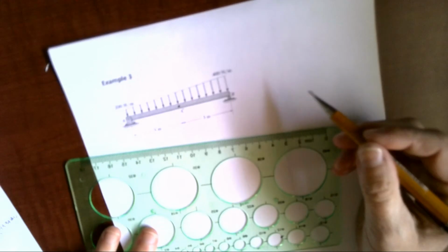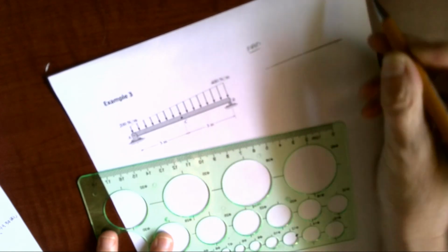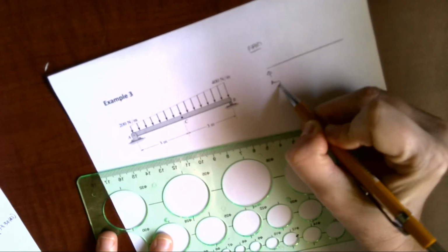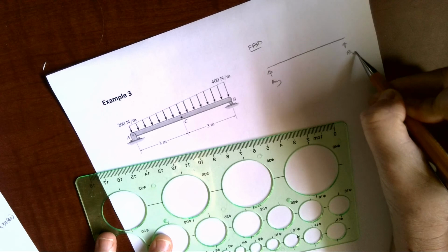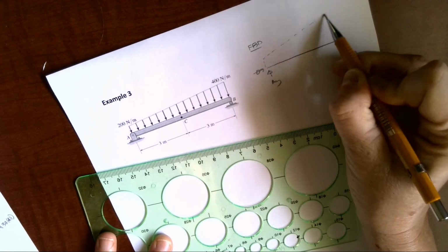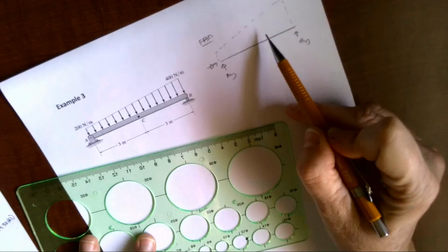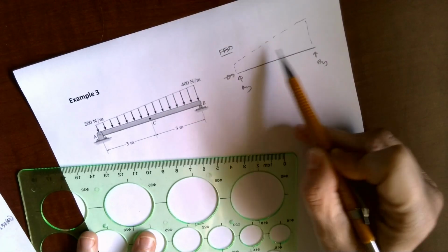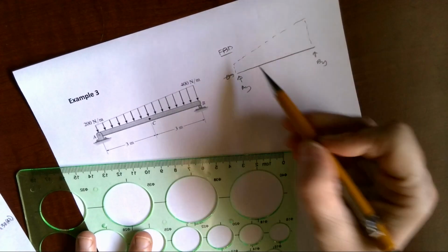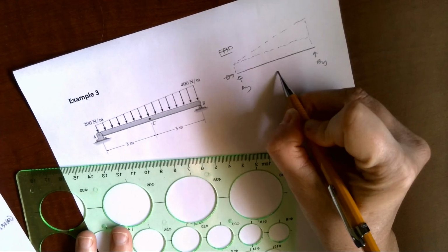So I'm going to draw a free body diagram overall, and I'm going to have an AY and a BY, and I know AX is 0 by observation. And then I have a load that looks something like this. Well, I don't really know what the equation is for the centroid of whatever this shape is. I'm sure there is one. I just like to go back and use kind of regular shapes. So I can break this up if we wanted to.